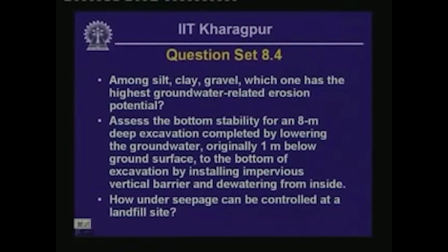The second question that I asked was for you to assess the bottom stability for an 8-meter deep excavation completed by lowering of groundwater, originally 1 meter below the ground surface, to the bottom of excavation by installing an impervious vertical barrier and dewatering from inside.